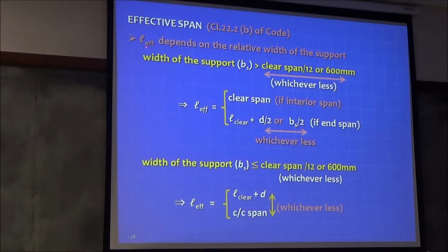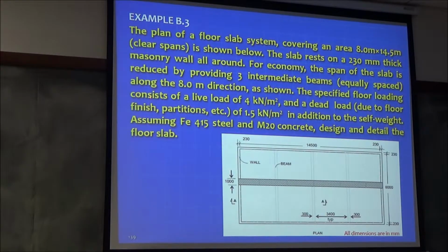So first, you should know the definition of effective span. Please go through this. We've covered it briefly. It also depends on the width of the support. If you have a very wide support, then you shouldn't worry about it. You should take clear span plus half. Now let's look at this problem.